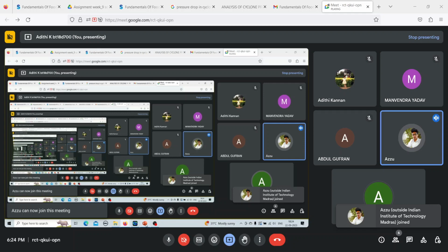So which of these is true about flotation? As the name suggests, things can float only if they are very light or very fine. If you have a very heavy particle, it will not float, it will sink. At that time you will use a process known as sedimentation, not flotation. Flotation is used in case of settling the fine particles. If you have a liquid which has very fine particles that need to be separated, you put it in a flotation device which generally has an agitator.